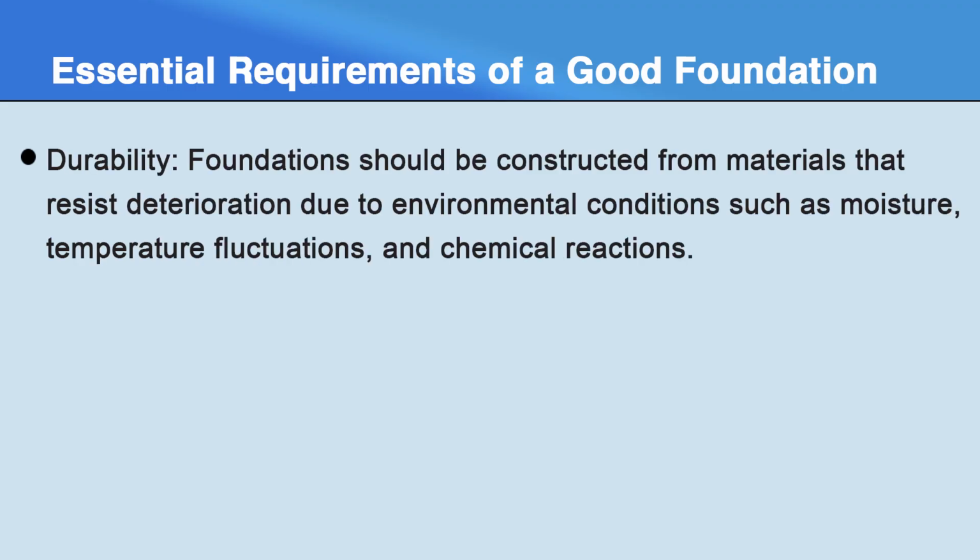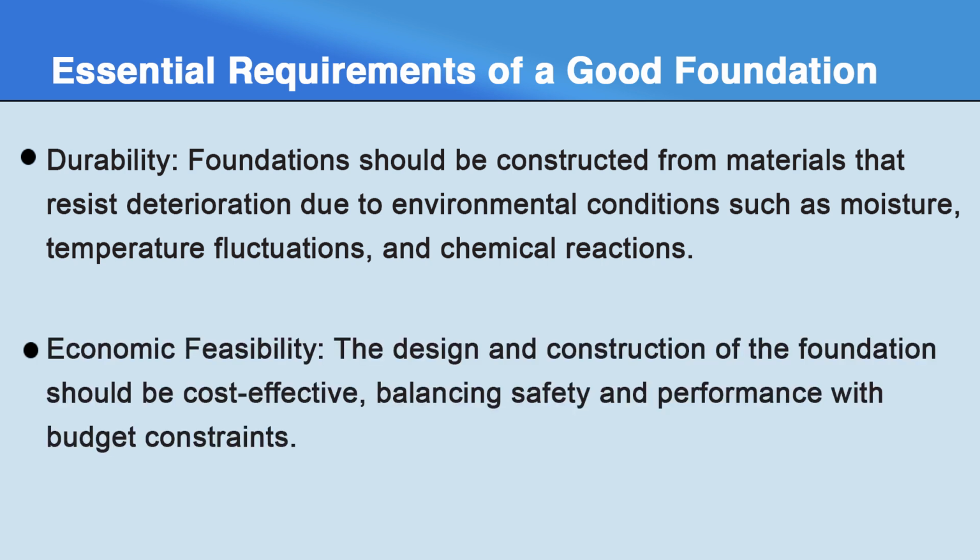Thorough planning and site evaluation are needed to understand current and future conditions that may affect the foundation. Employ flexible foundation designs that can accommodate potential changes, and ensure proper drainage systems are in place to manage water flow and groundwater levels. The next is durability. Foundations should be constructed from materials that resist deterioration due to environmental conditions such as moisture, temperature fluctuations and chemical reactions. The next is economic feasibility.